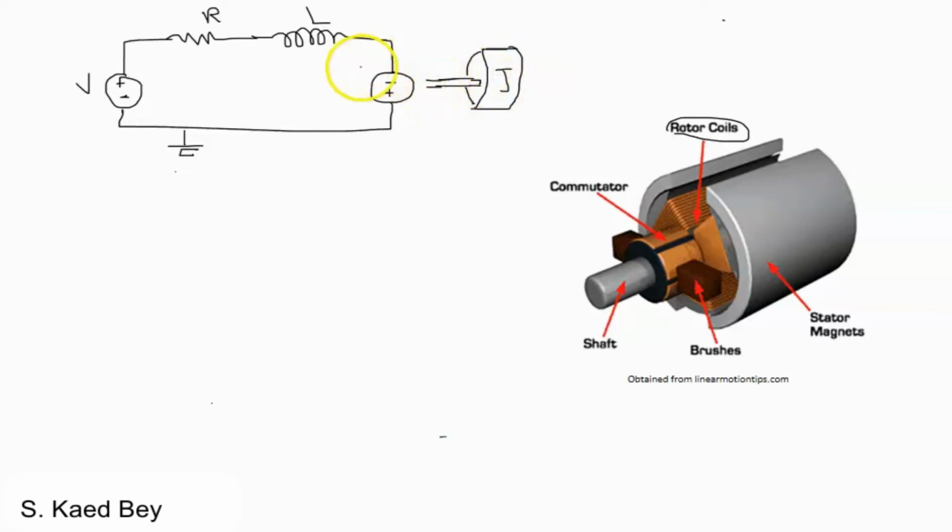And if we consider that the electric circuit applies the input torque as T, then this obviously will cause a motion in the direction of the applied torque as theta. The friction can be presented as a function of the damping coefficient B and the angular velocity, or theta dot.